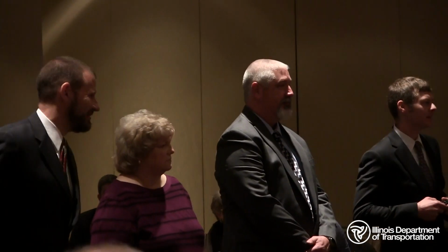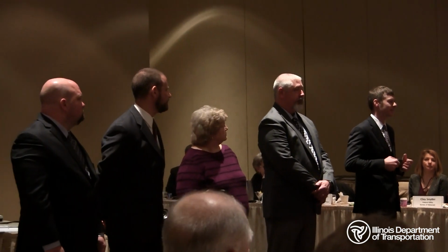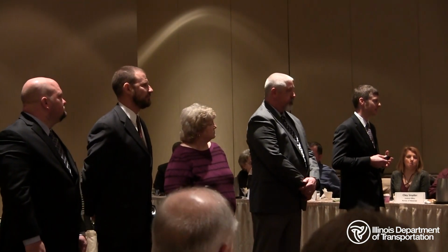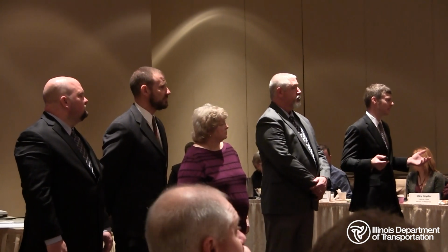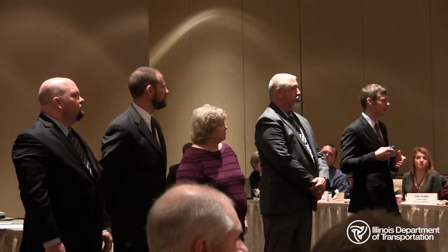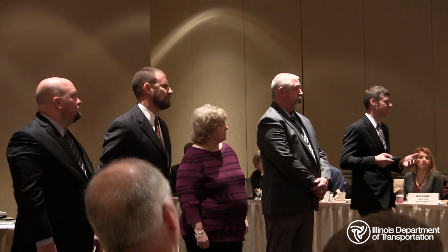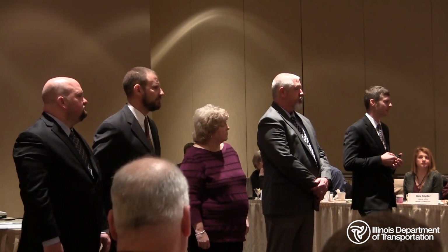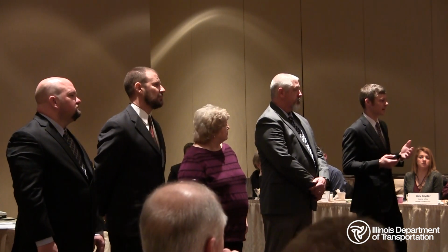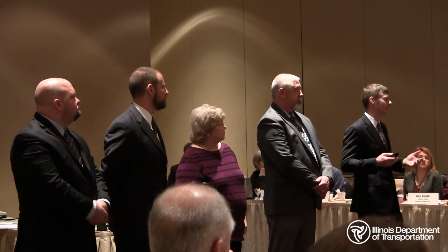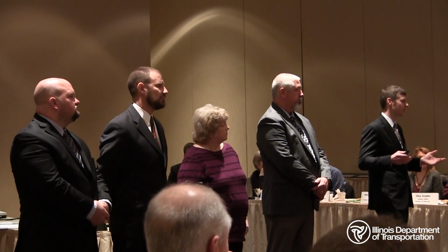So you're asking how the mobile LIDAR unit performs in congested areas, and potentially what times of day we can complete projects. Mobile LIDAR can acquire data at speeds of 55 to 60 miles an hour and still achieve a very dense point cloud. And data can be collected at nighttime to avoid congested traffic, as long as you don't need additional photographs. Most data contains intensity returns, and you can view that data in a way that you can delineate features without having photographs.